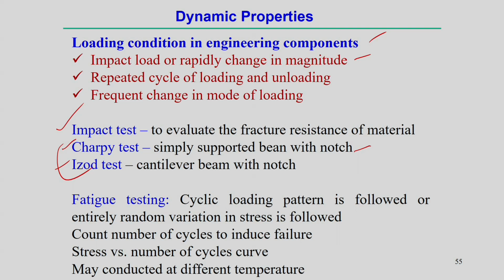Then, apart from impact testing, fatigue testing can also be done, because fatigue testing is normally done by the application of a cyclic loading pattern, which follows either an entirely random variation in the stress. Basically, when there is cyclic or dynamic loading, we need to find out the pattern of how the stress varies when we apply it to the sample or specimen. With this particular mode of loading applied to the samples, we then count the total number of cycles to induce failure.